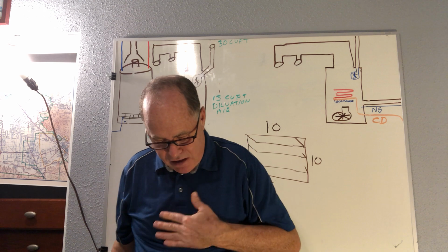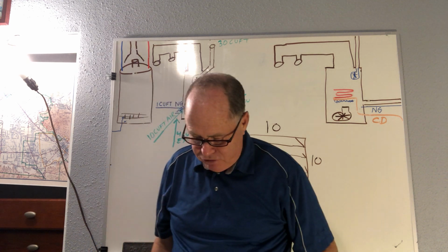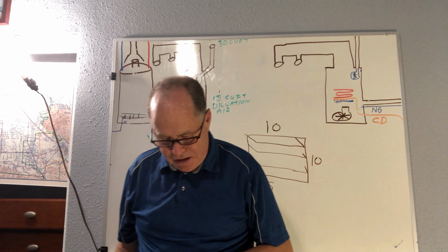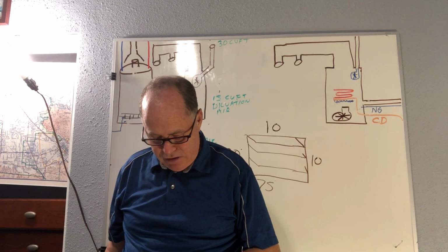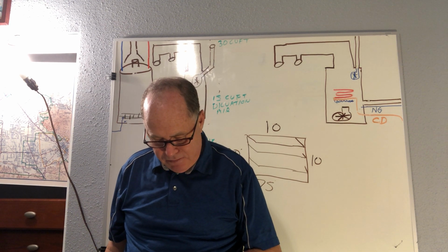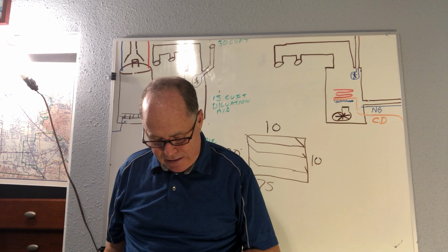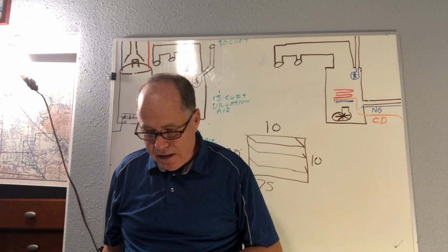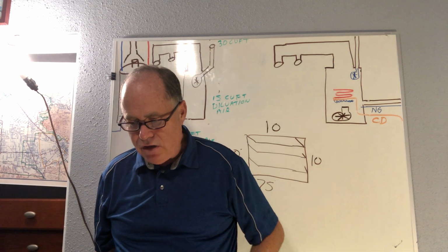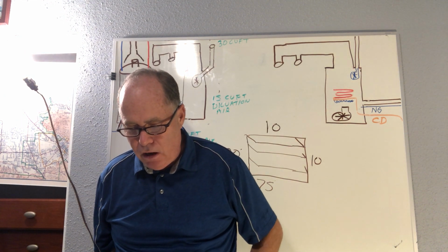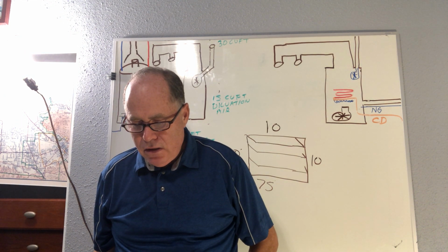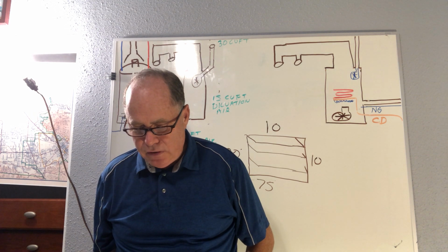Okay, here it talks about ducts shall not be screened where terminating in an attic space. Why? This is to prevent the possibility of obstruction of the duct when insulation is blown in the attic, a popular method for insulating a building. If no screens are installed, the blown-in insulation would simply fall in the compartment and alert the observer.